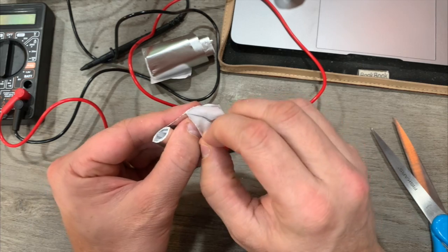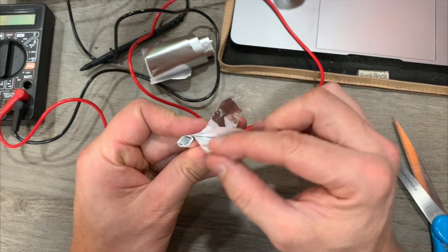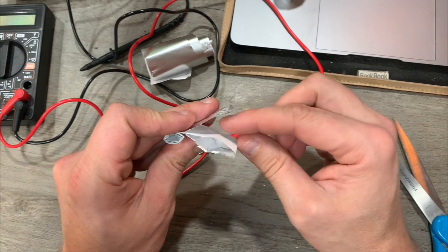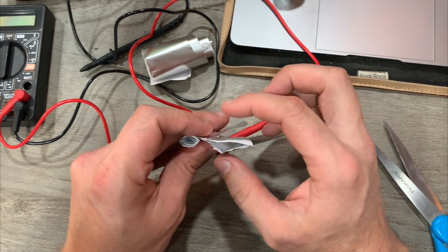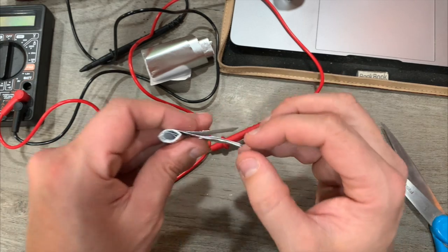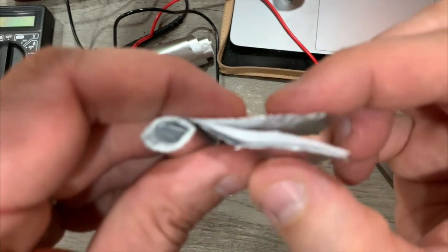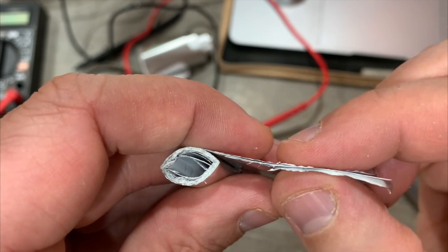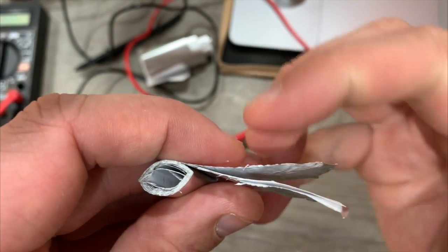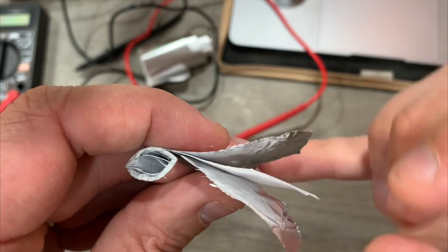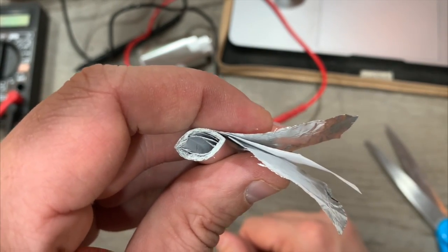The two ways that you can increase the capacitance, and I'm going to demonstrate this in the simulation, is by increasing the surface area. So the larger the surface area, the larger the measure you're going to get for capacitance. And the second way is by closing up the distance between the two metals. The shorter the distance, the closer they are to one another, the higher the capacitance, and the further away they are, the lower the capacitance.